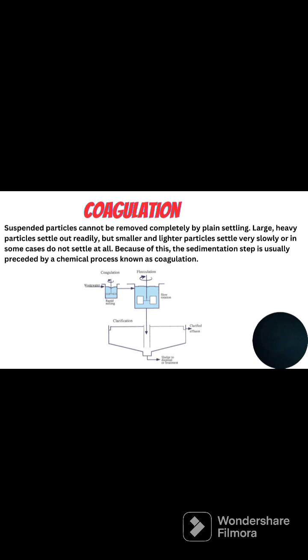The suspended particles cannot be removed completely by plain settling. Large heavy particles settle out rapidly, but smaller and lighter particles settle very slowly, and in some cases they do not settle at all. So some coagulants are added, and then the water is treated here by the settlement process.